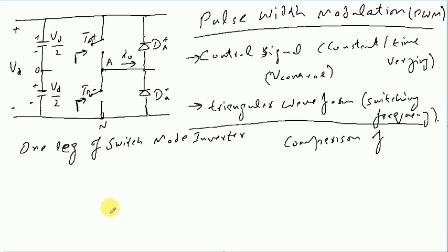In the discussion about the three categories of voltage source inverters, for the pulse width modulation type of inverters we mentioned that the inverter is capable of controlling both the magnitude and the frequency of the output voltage waveform. So basically this triangular waveform, whatever the frequency it has, is the frequency of the output signal.